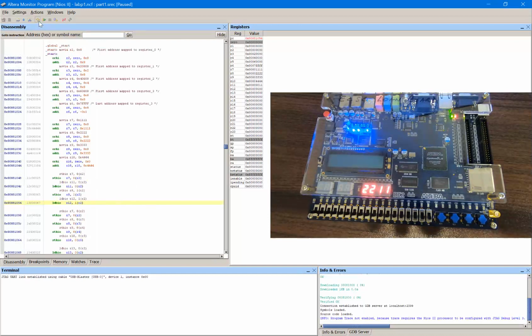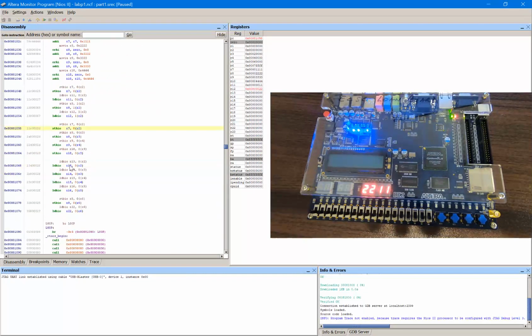And then it will load that value back into R12, and that worked fine. So that was verifying that that worked. Now, to verify 16-bit transfers, we're going to do store half words and then load half words back. First we're going to do a store half word, and each of the addresses used is going to be mapped to a different slave register, because we've put the addresses at the start of each of the slave register mappings. So we will do all that.